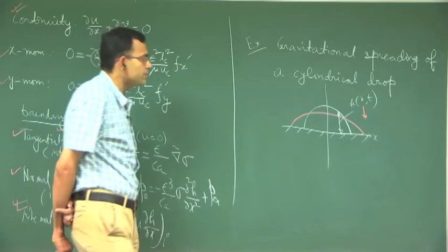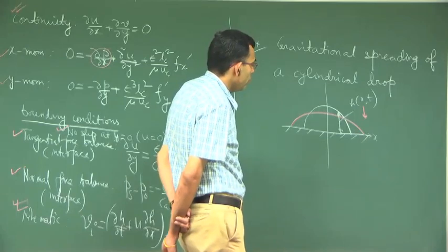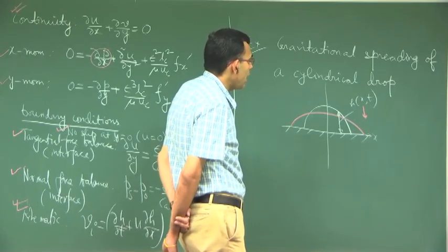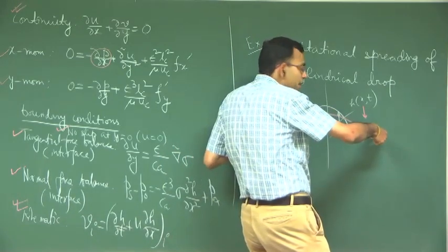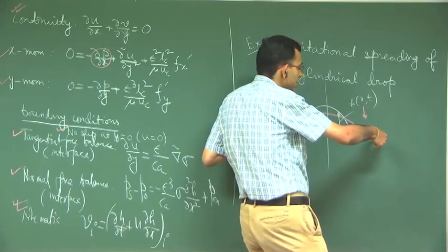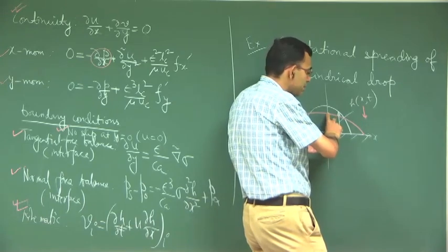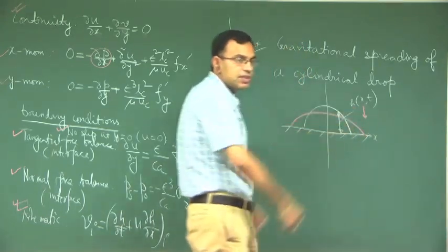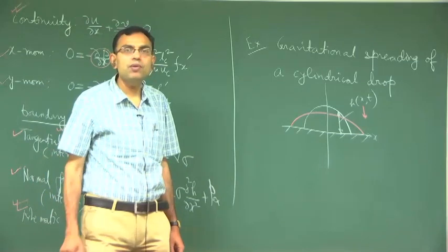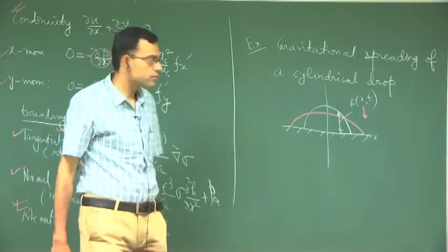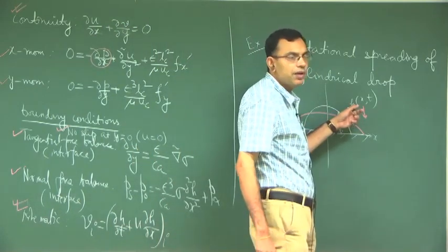At some point of time, you will have a situation when this entire droplet is spread on the surface, in the sense that this maximum height is 0, and when this maximum height is 0, we say that the spreading process is complete. So, one of our great interests will be what will be the spreading time, or in general how will this h depend on x and time.